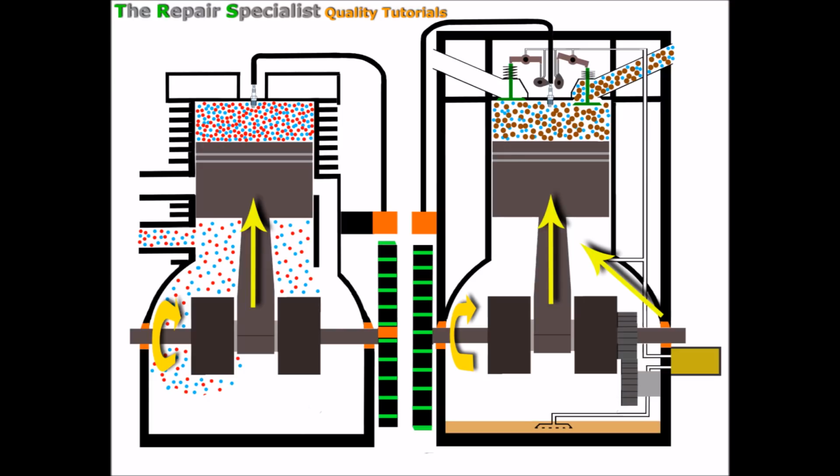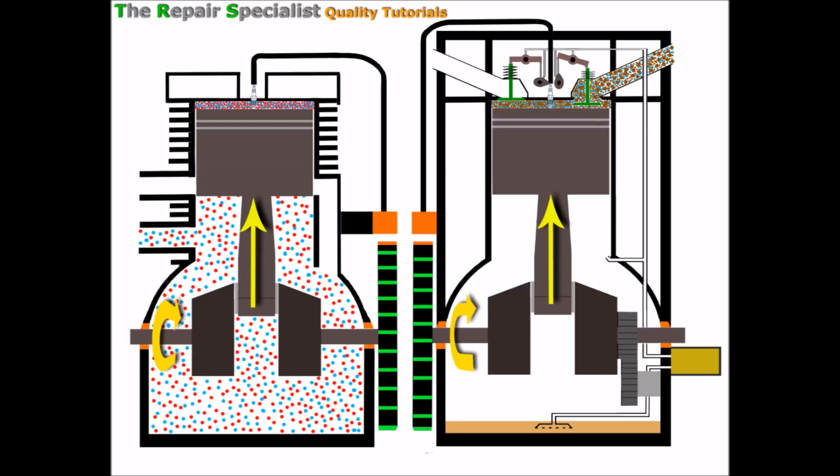So again, with each piston in this position, if we look at the magnets on the flywheels, there's the one on the two-stroke and the one on the four-stroke in the same position on the side we can't see. We'll see there that they are now positioned 90 degrees before the coil packs, so that when the pistons actually get to the top dead centre, they'll be passing the coil packs 90 degrees later, if you like. And there we go, we can see that now. So now both pistons are at top dead centre, and what's happening between the two pistons is very, very different.